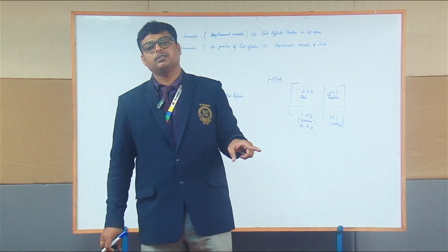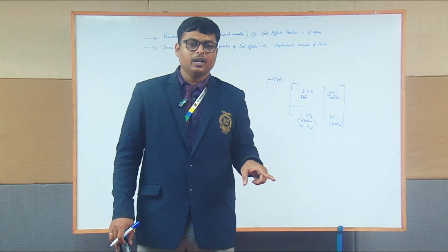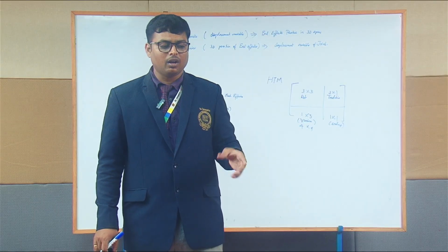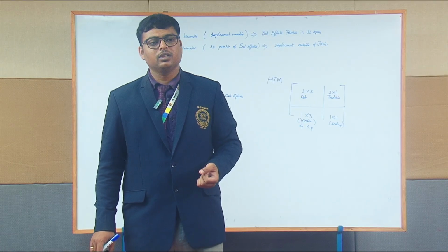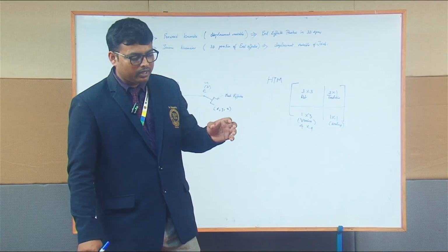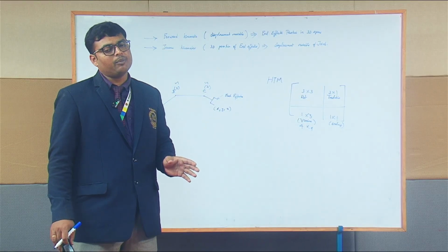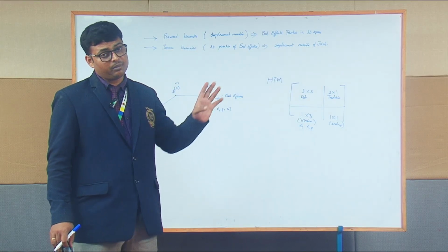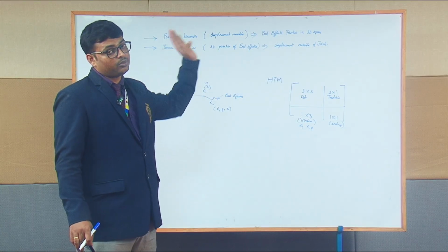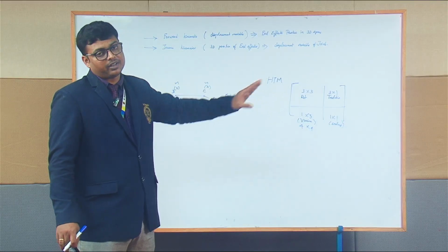For computing this, we need to know the DH rule, Denavit and Hartenberg's principle, or theory. Denavit and Hartenberg together created a principle for computing the displacement variables into a table, after which it can be projected to a homogeneous transformation matrix.